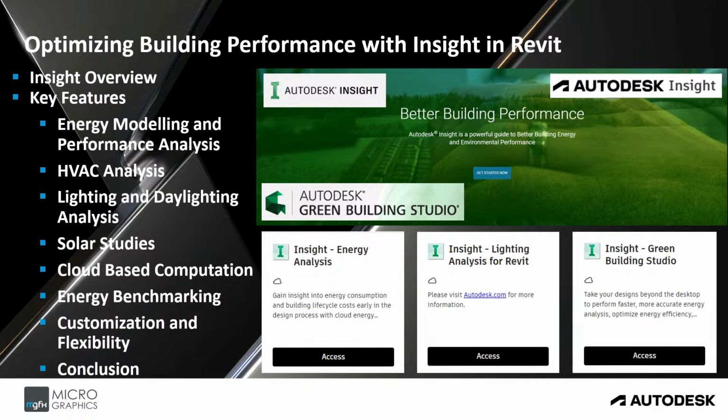Customization and flexibility. Users have the flexibility to test various scenarios by adjusting parameters like occupancy, material choices, and insulation types. This adaptability allows designers to customize simulations according to the specific needs and constraints of each project. By tweaking different parameters, architects can identify the most sustainable and cost-effective solutions, minimizing environmental impact while maximizing building performance.